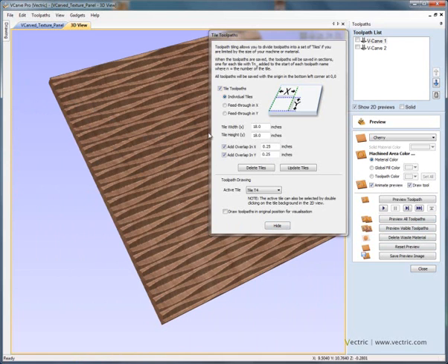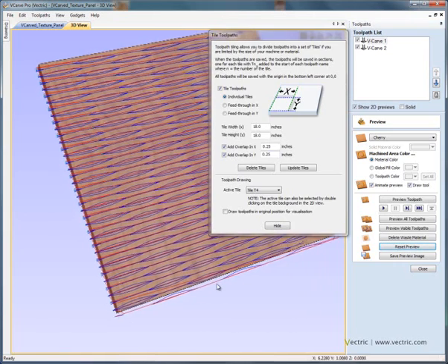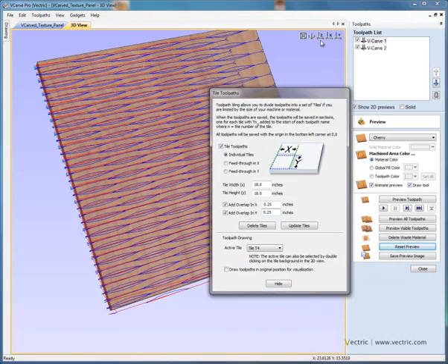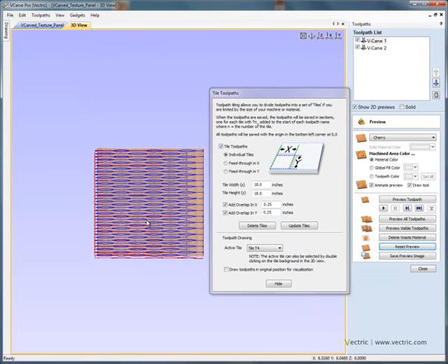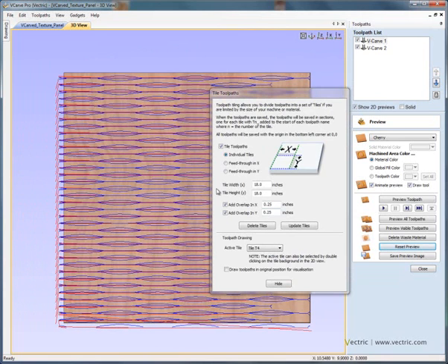We can force the toolpath to overcut, which is what we're doing here. We're saying overcut by 1/4 of an inch. If we reset the preview block for a moment and view straight down the z-axis, for this particular tile, tile number 4, the software is overcutting by 1/4 of an inch in X and Y, and you'll see that that's the 1/4 of an inch along each axis.